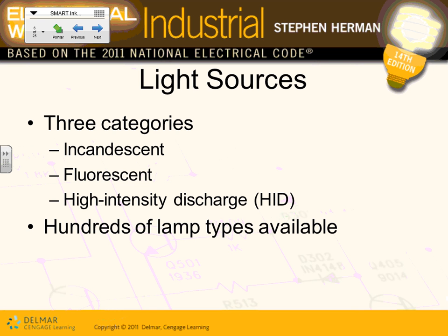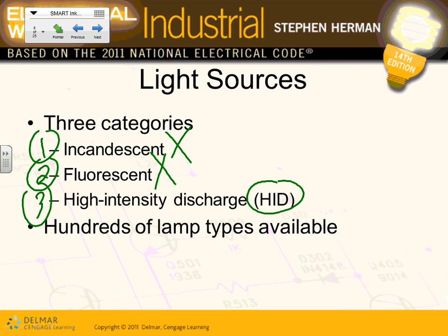Now the lighting sources. There are three lighting sources. We studied lighting intensively, guys, in the fall. Do you remember when we talked about lights in detail? There's incandescent light, source number one; fluorescent, source number two; and high intensity discharge, source number three. Drop incandescent and fluorescent when it comes to parking lot lights and outside lights for the most part, and your option really is high intensity discharge lamps. And we didn't do a high intensity discharge lamp this time, guys.